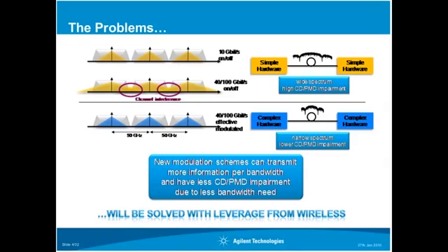You rather talk about symbol rate now instead of bit rate. Essentially what you're doing is keeping the symbol rate low, and you are coding more bits into one symbol. If you take a look at the symbol rate, you will find that at 100 gigabit it can be around maybe 27 giga symbols per second. And due to the low symbol rate, you get a lot more tolerant against linear impairments like PMD and CD. That is what people see as a big advantage in the new 100 gigabit approaches.